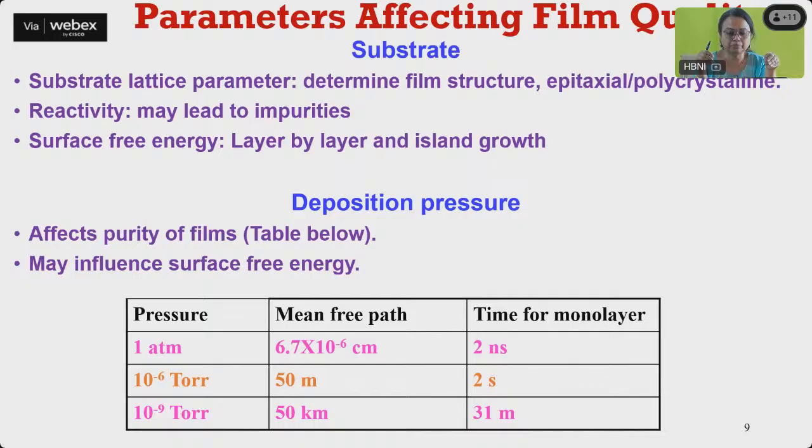Second is the deposition pressure, like what is the pressure inside your deposition chamber at the time of deposition. Why it is important is that it affects the purity of your film. If the vacuum is not very good and you are depositing at a high pressure, then the gas atoms, like in the case of sputtering, which we will be studying today, where we have argon, can get incorporated.